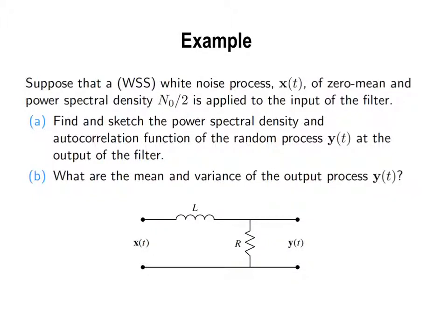So when we say noise in a communication system, we only care about either man-made noise, which is the interference, or the noise that comes due to the electronics. The things that come due to radiation and all these things, first of all, are in bands that are different from the bands that we are receiving from. So they are already filtered out, right? And second, even the remaining parts are very low compared to the thermal noise, so you can simply ignore them because thermal noise is going to be your dominant factor.